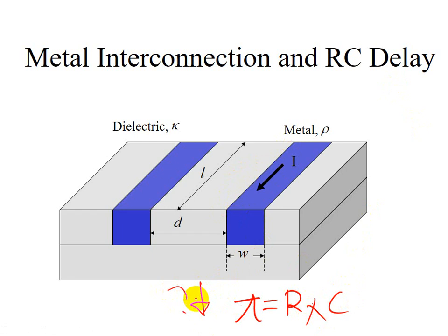That means reduce, first, the resistance. Can you lower the resistance of the conducting wire? Yes. You used aluminum in the past as a conducting wire and changed it to copper right now. You are actually reducing the resistance, so you can come up with a lower time delay.